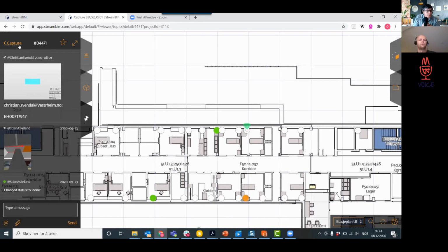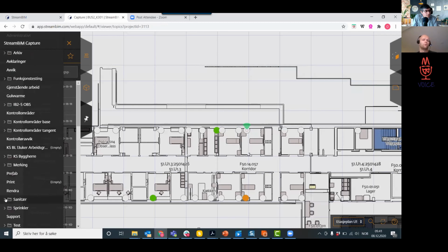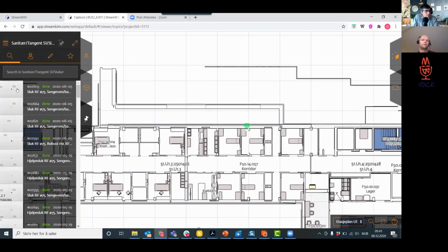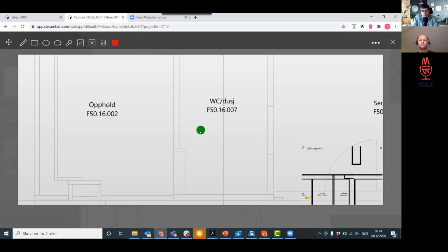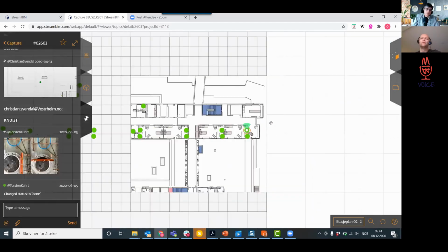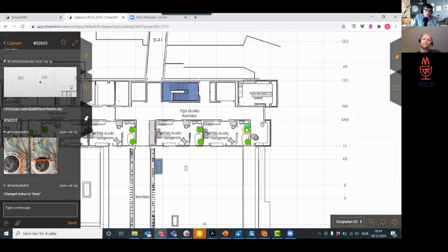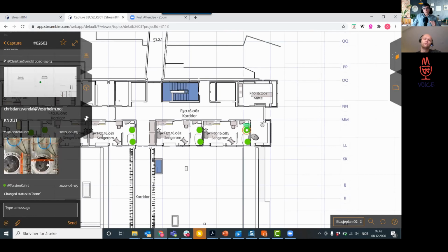They've done that for a lot of different equipment. So drains are different, but the same. If you go to sanitary and one of those strings, same thing here. They use Solibri to identify all the drains, but the difference is that they look down instead of looking up because they want a location in each room. And if you zoom out here, you will see that these are all drains in this building on this floor level. You have the same IDs as well, different types, but in this case, they also used it for QA.